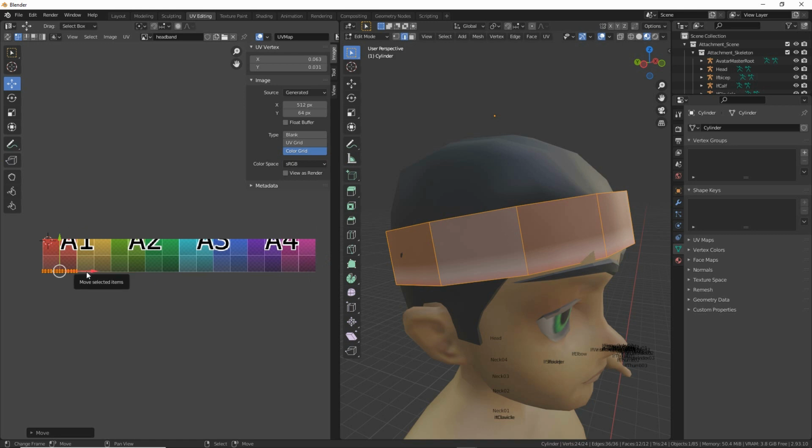So as this is a regular sized object, what we can do to scale this uniformly is lock the cursor, so that's this thing, down into the bottom corner. So we want view, change the coordinates, so click type 0, 0. The cursor's drop down to this corner.